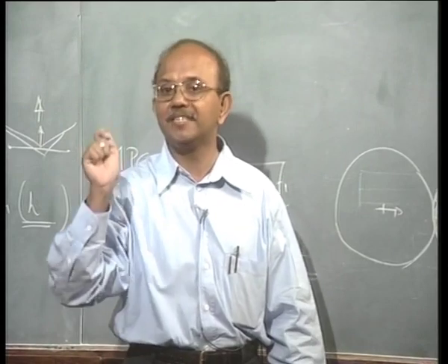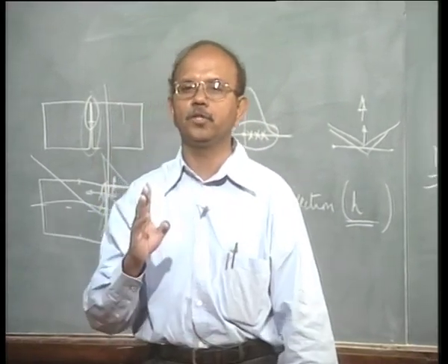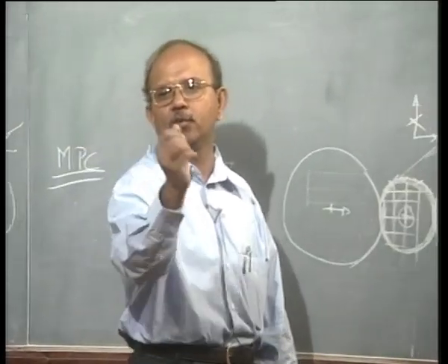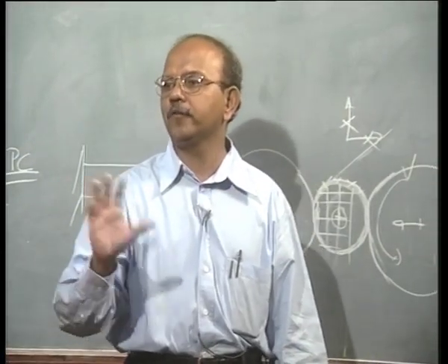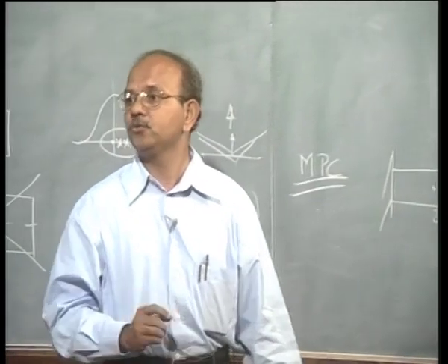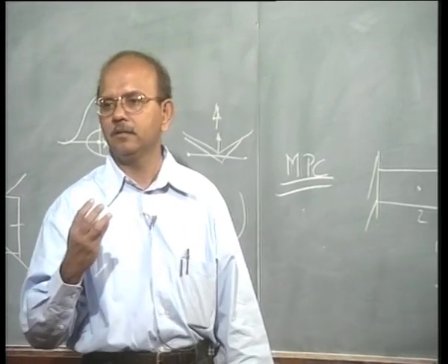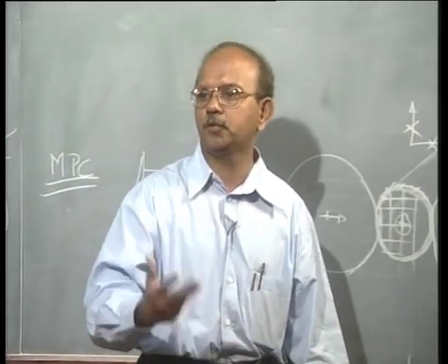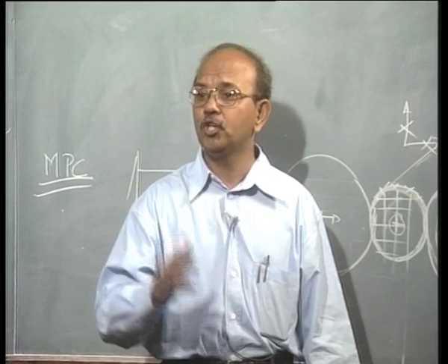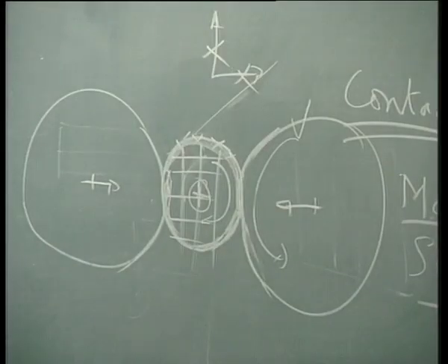Yeah, that's beautiful. So it is capable of rotating. See, any time you put a boundary condition, when you want to remove singularity, don't blindly go by the rule that I have fixed one node in the x direction and one node in the y direction, and so I have fixed both the directions and hence I am very safe. No, you should go and look at whether rigid body motion, rigid body velocity or displacements are possible, in spite of you fixing these nodes. Now you have fixed these nodes, as he correctly said, it may start rotating.